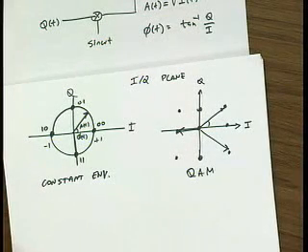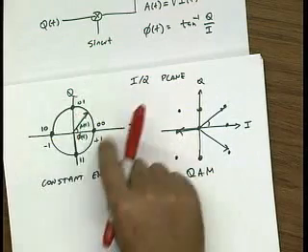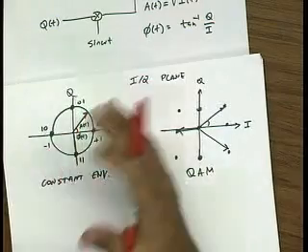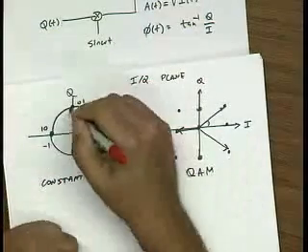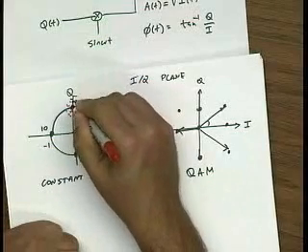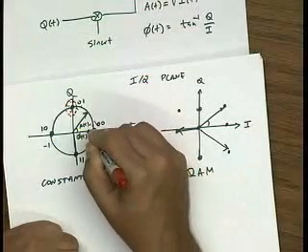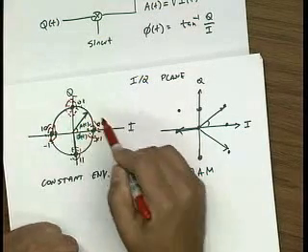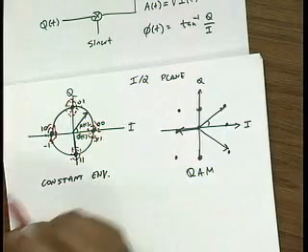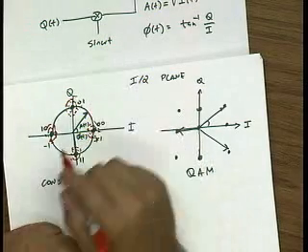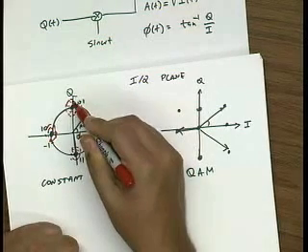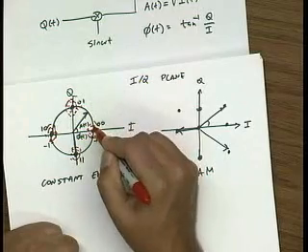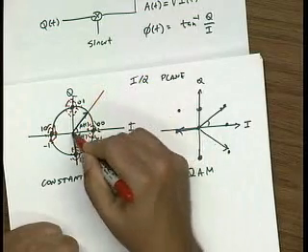And we talked about this briefly before, because if I transmit bits on this, what we call this constellation, what we receive are not actually these points exactly, because there's going to be noise in the system. So what you would actually receive, if you drew a bunch of bits that you received, they would generate, let's say, some scatter plots with clusters of points close to these original IQ points. And you can see that if you had to make a decision about if this bit were sent or if this bit were sent, you could be fairly confident that you're making the right decision, as long as, let's say, you're in this quadrant.